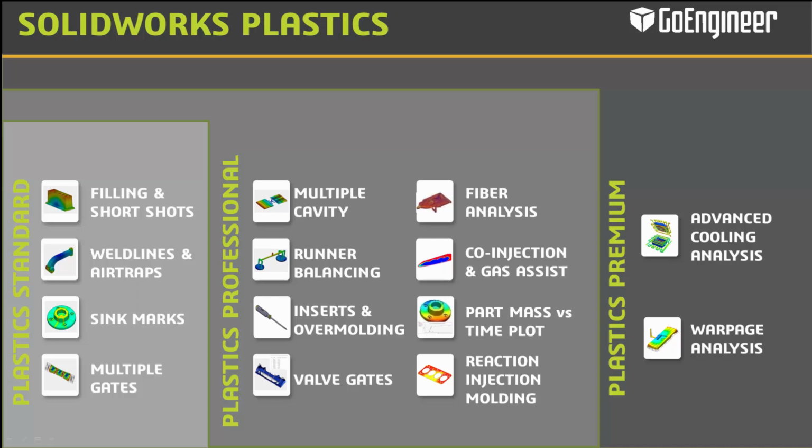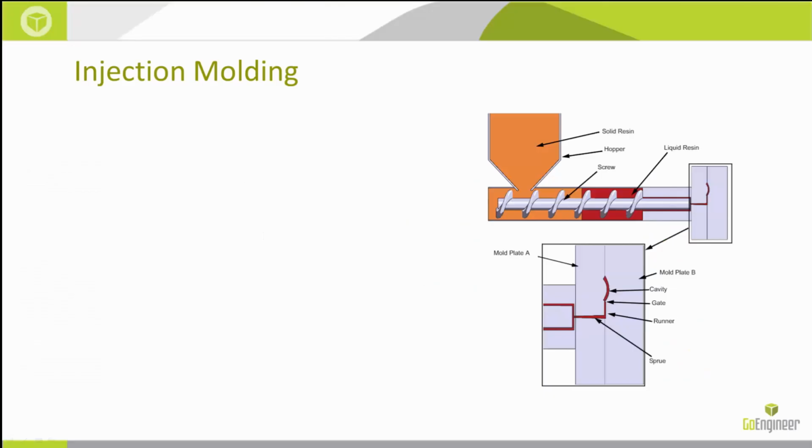The simulation includes filling, packing, cooling, and warp analysis. So the tools within these help design and verify our gate and runner designs as well as cooling line layouts. Also, with SOLIDWORKS Plastics being fully integrated into the SOLIDWORKS platform, the user has the ability to quickly make changes and rerun analysis to validate the part and mold design prior to production of the injection mold. During my webinar, I'll go over some basic stuff on the injection molding process, and I'm also going to point out a few of the pain points in the injection molding process and during the part design and mold design phase, and show how SOLIDWORKS Plastics can help with those.